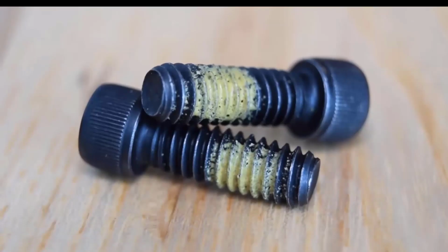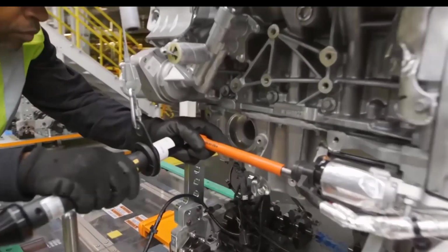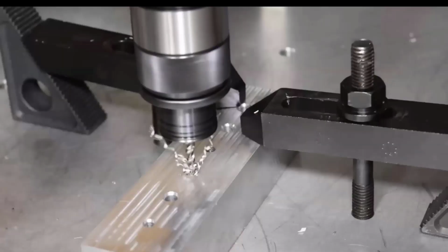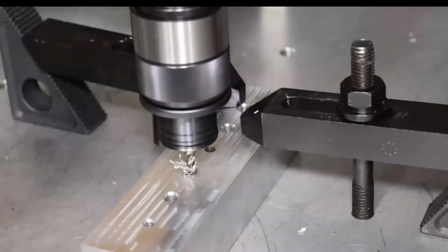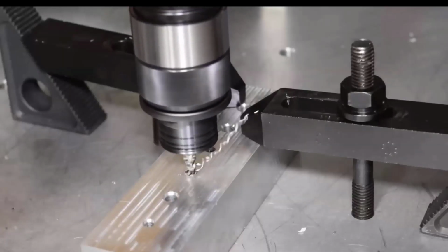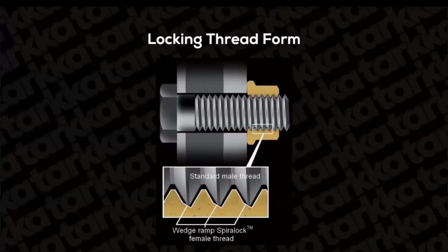Mass-produced products often use fasteners with a nylon patch that is pre-applied to the threads. This isn't as effective as Loctite, but it is a lot faster to assemble. There are also proprietary tabs that cut a special thread form that is compatible with standard fasteners. The modified thread geometry creates a locking effect that makes the fastener more difficult to remove.